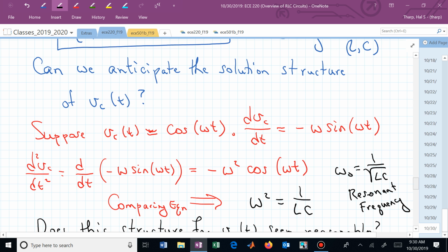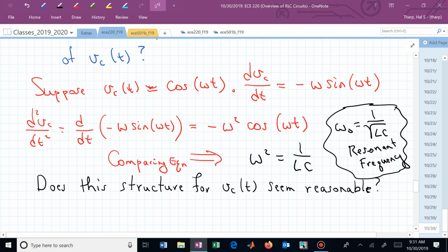and we use that all the time. When we tune our radio, we actually have this tank circuit, and it likes to oscillate at specific frequencies. In the old days, you'd tear a radio apart and you'd see this big capacitor in there, these plates moving, and you're adjusting that as you adjust the dial. You're tuning this resonant tank circuit, and when it gets to the right frequency, you get your radio signal that you want. Good use of a tank.